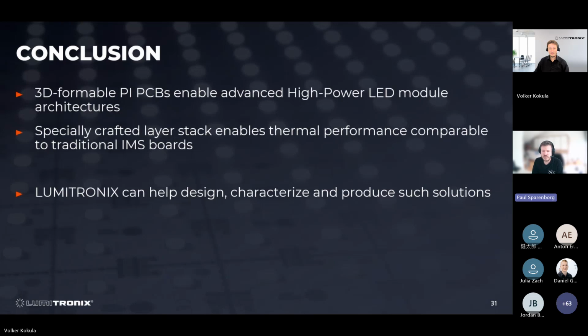We have one more question from Christoph Seibert. I'll translate to English. Have the tests been conducted with screws without thermal interface material? Yes, the test results presented here were done for screwing without thermal interface material. The reason is that since the devices under test are very small, in this case we can have a very consistent and good contact by screwing.